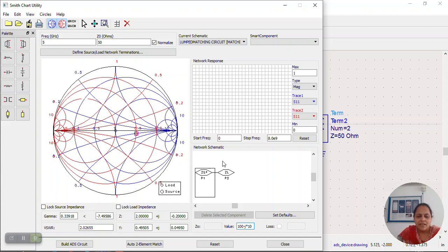When I press Enter, you can see the location of the source impedance, and the middle one is the load impedance. The load is shown in the middle because I have chosen 50 as the middle point of the Smith chart. Now, how can I construct this Smith chart matching network for these two impedances? I have to move from my ZL to ZS star.